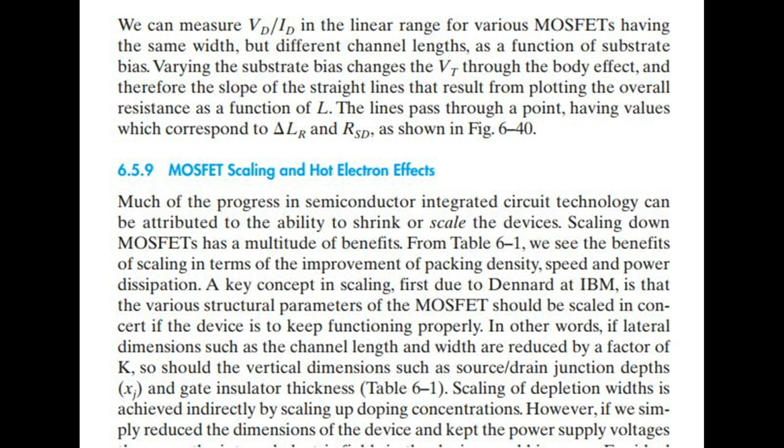MOSFET scaling and hot electron effects. Much of the progress in semiconductor integrated circuit technology can be attributed to the ability to shrink or scale the devices. Scaling down MOSFETs has a multitude of benefits. From Table 6.1, we see the benefits of scaling in terms of the improvement of packing density, speed and power dissipation. A key concept in scaling, first due to Dennard at IBM, is that the various structural parameters of the MOSFET should be scaled in concert if the device is to keep functioning properly.